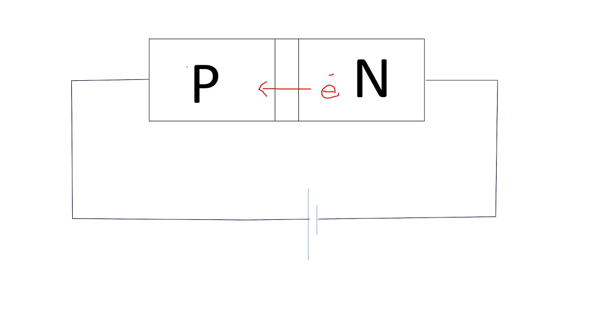that is photons. For silicon and germanium junctions, a greater percentage of this energy is given up in the form of heat, so that the amount emitted as light is insignificant. But in the case of other semiconductors like gallium arsenide, gallium phosphide, and gallium arsenide phosphide, a greater percentage of energy released during recombination is given out in the form of light. If the semiconductor material is made translucent, light is emitted and junction becomes a light source.